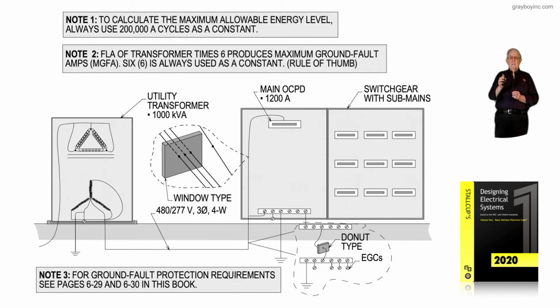And the grounded conductor connects to that bar. But notice that the leakage current due to a ground fault has to come back over your equipment grounding means, designed and installed by 250.118 of the NEC. So the window's the best type, but it naturally costs more money.